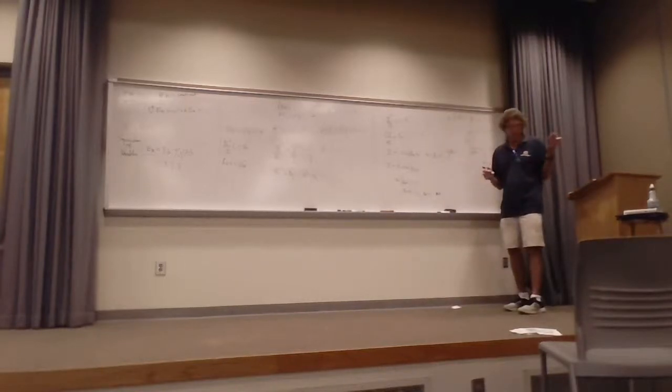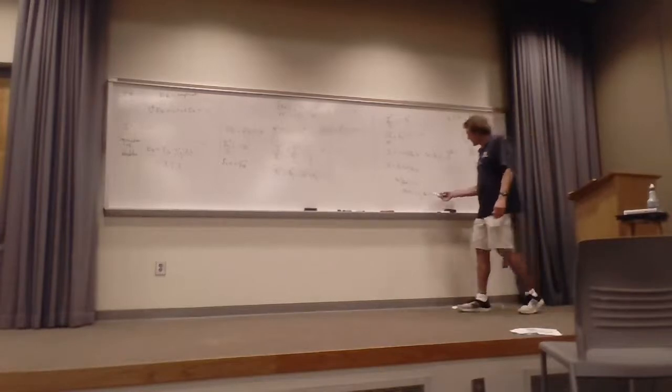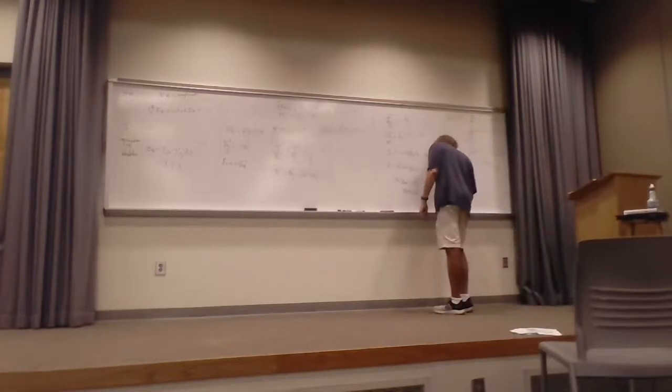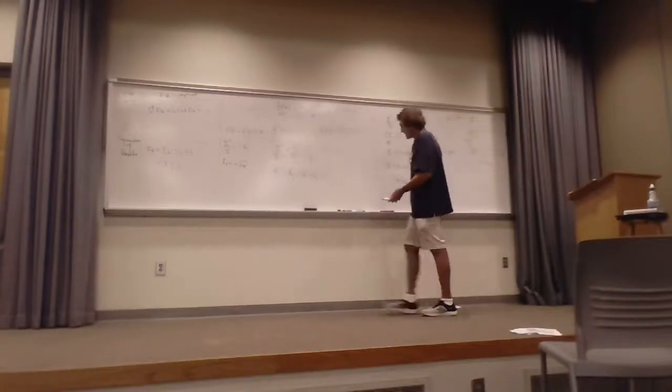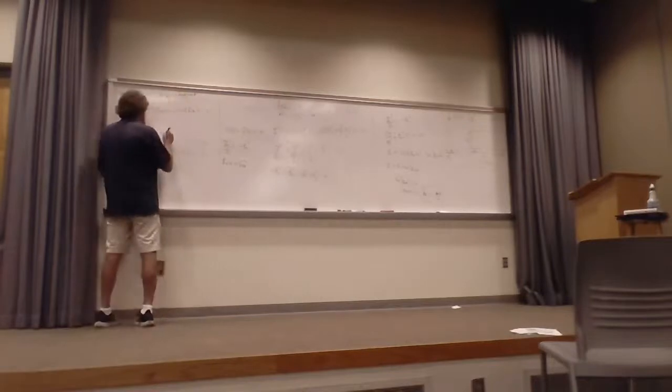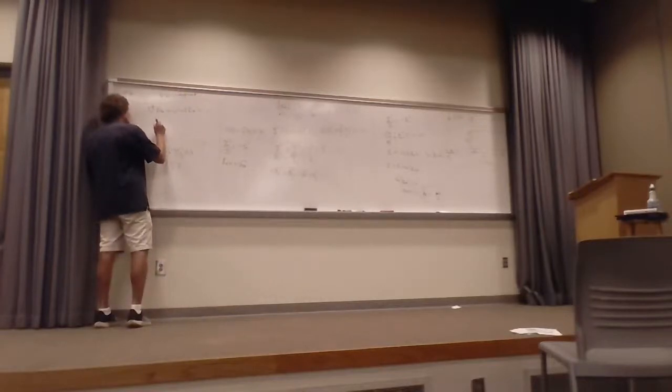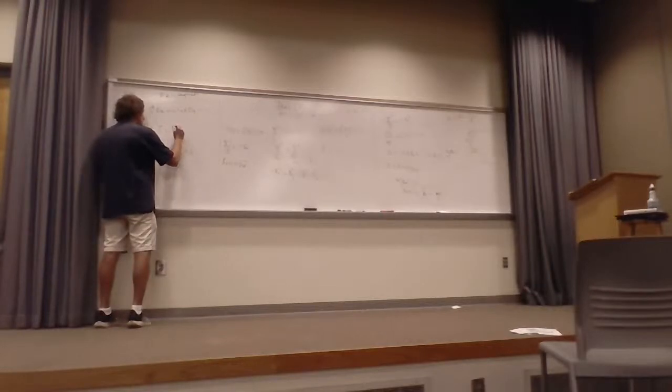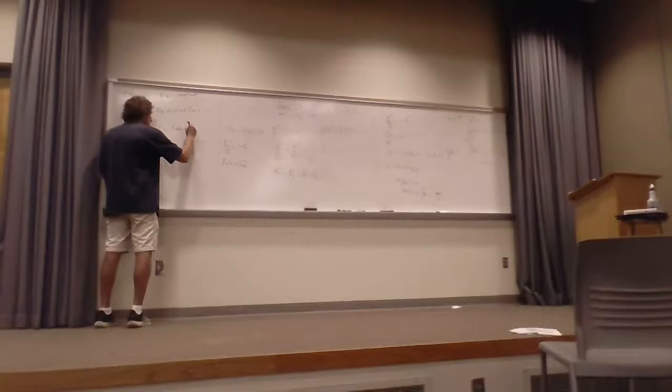It can be any integer, but it's an arbitrary one. And then I divide by a. So lo and behold, I have my value for beta x. And now I'm going to create the solution right here. I'm going to say that my E_z is equal to some E naught. First one is going to be the sine of m pi over a times x.